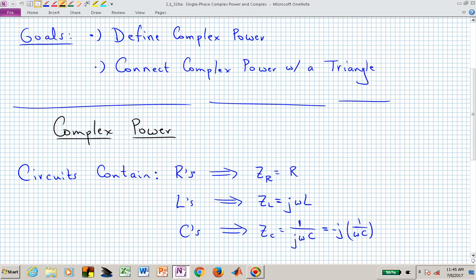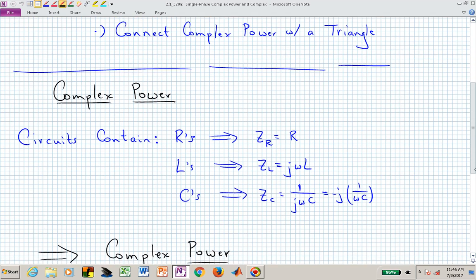So you can see that the impedance of the inductor, if you think about j's giving you a vertical displacement, which is orthogonal to the real component, which is the resistive component. The inductors go up, the capacitors go opposite to that, or they actually go down in our complex plane.